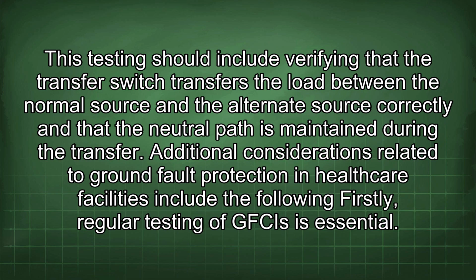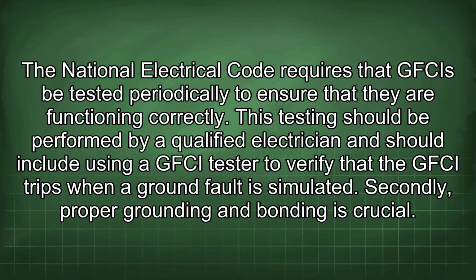Additional considerations related to ground fault protection in healthcare facilities include the following. Firstly, regular testing of GFCIs is essential. The National Electrical Code requires that GFCIs be tested periodically to ensure that they are functioning correctly. This testing should be performed by a qualified electrician and should include using a GFCI tester to verify that the GFCI trips when a ground fault is simulated.